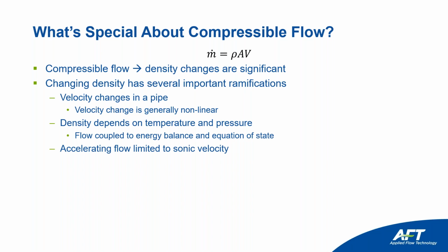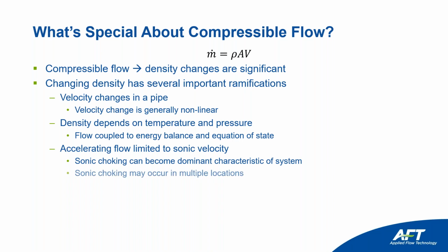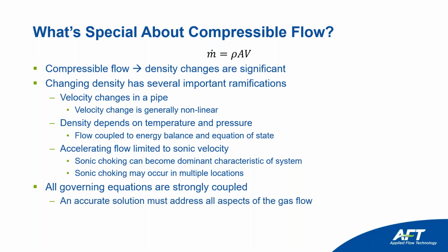You can potentially have sonic choking if your gas velocities are reaching the speed of sound. Sonic choking can also become a dominant characteristic of your system. You can have multiple choke points throughout the piping network of your system. And ultimately, all of the governing equations that are solved together are strongly coupled together, and they need to be handled properly in order to correctly account for gas flow.